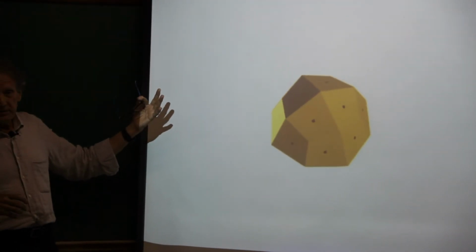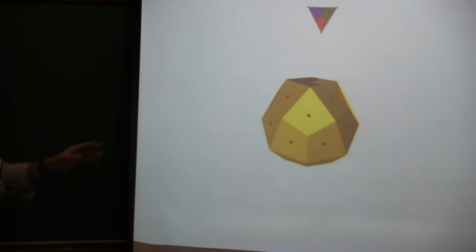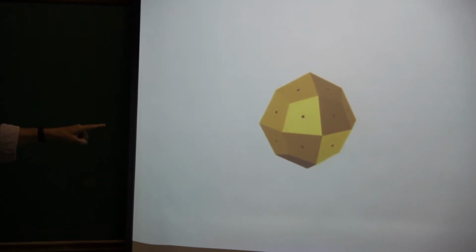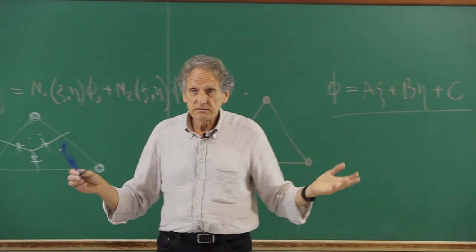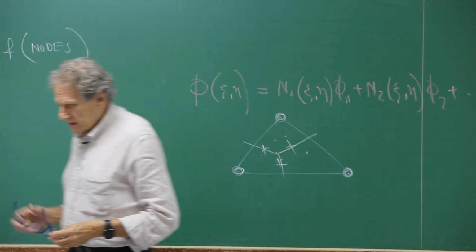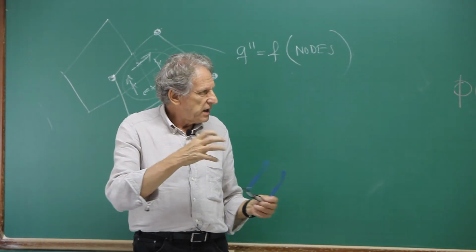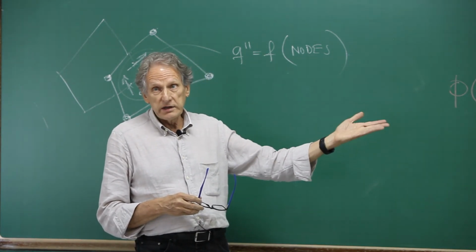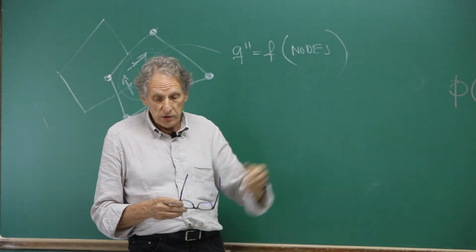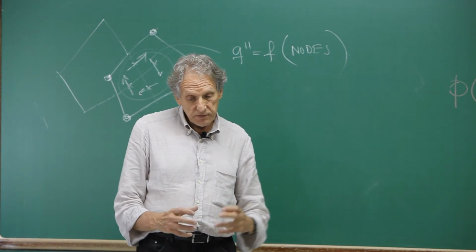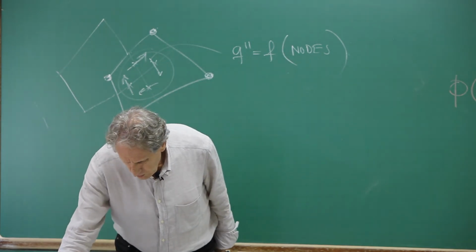There are some flying triangles, tetras here, but this is the control volume, the 3-dimensional control volume, which results in the construction using tetras in a 3D situation. Then we can see a little bit more clearly how, in order to build the control volume using tetrahedrons, you have to put 8 tetrahedrons together, and one part of each one generates the control volume.